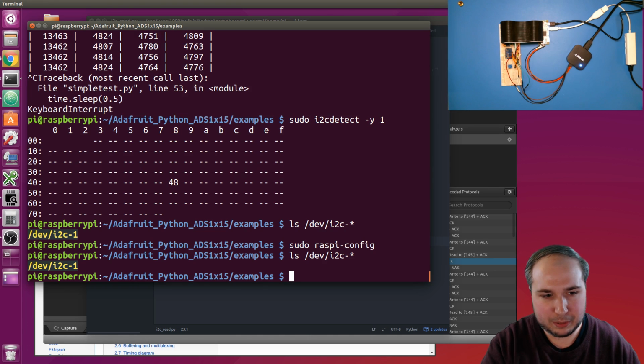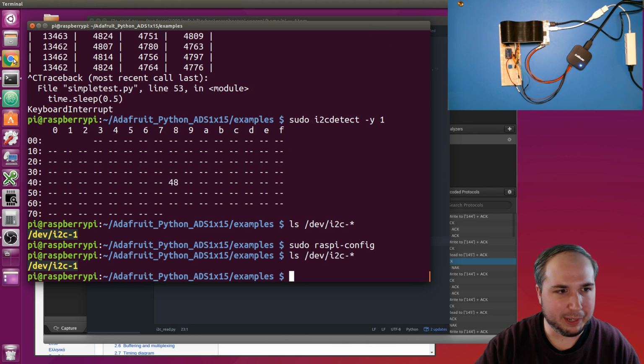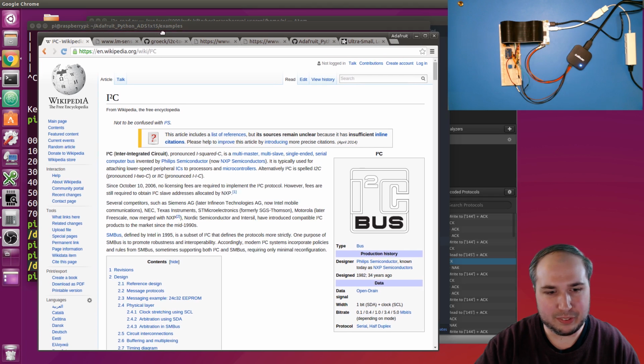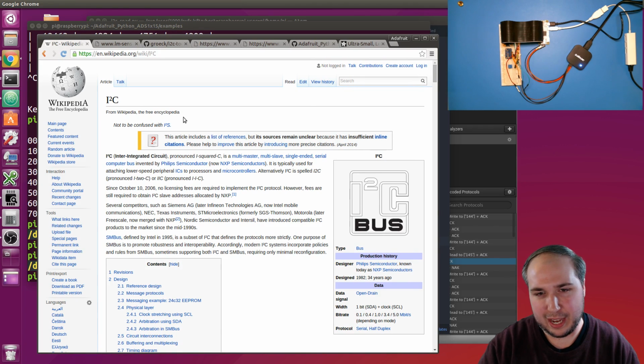So there's this device under the dev node that gives you this I2C interface. Now the code to actually talk to this thing, there's a Python library called smbus, and smbus is actually a subset, from what I understand, of I2C. I think there were devices on motherboards, things like temperature monitors, that use the I2C protocol, but they use this subset called smbus that basically doesn't have all the capabilities.